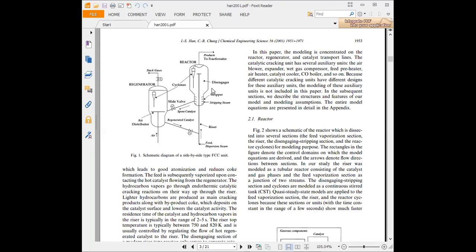catalyst formation or catalyst regeneration, so you can say this is a riser, this is your regenerator, this is the air supply, and here you have the air line, and here there is an air distributor. Okay, and from the bottom, as I told you earlier, feed will be given to the riser. Okay, and this is the sweeper or sweeping steam, then a cyclone is provided. Okay, and you can take out your desired product, right? So